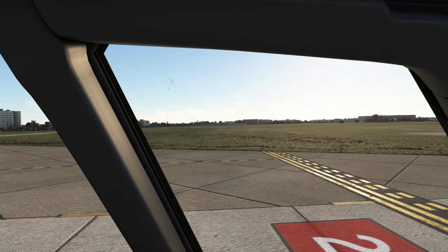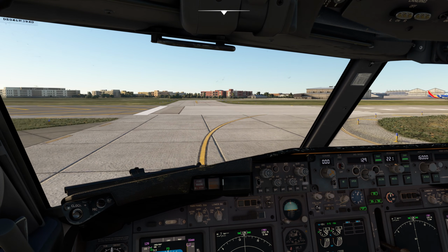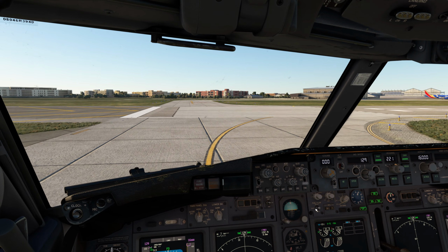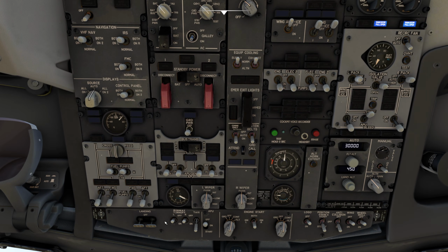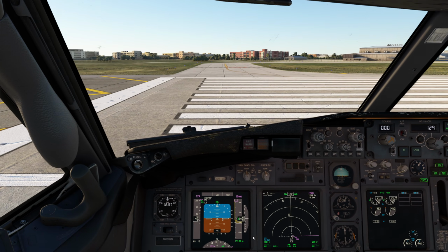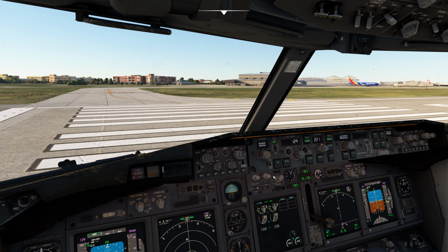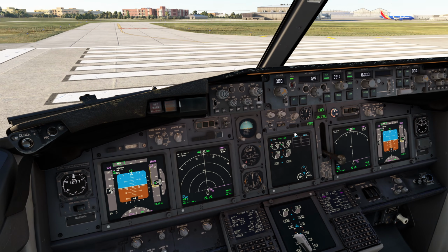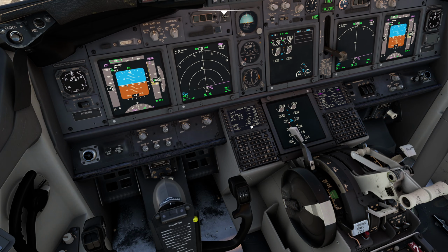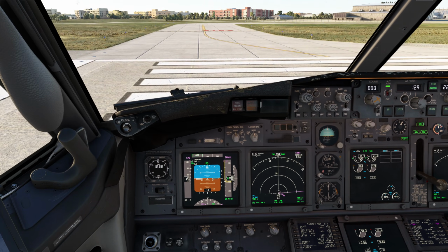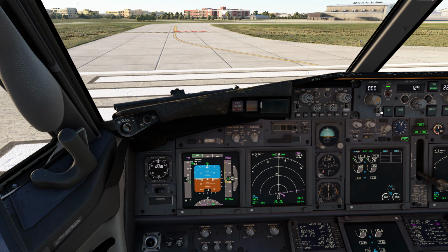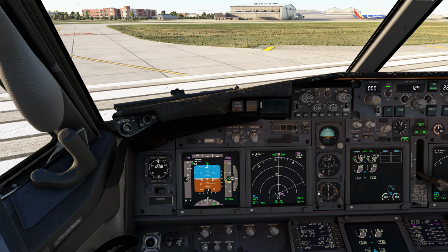Okay, so let's just look to our left. Looks clear. Let's get our lights on. Landing lights come on. Runway turnoff comes on. We can turn off taxi, and strobe and steady comes on. And we'll attend the flight attendants, let them know that we are cleared for departure. LNAV, VNAV is armed. Auto throttle is now armed. RTO is set. Flaps 5. Rotation is 129 set in the MCP. Let's get lined up.